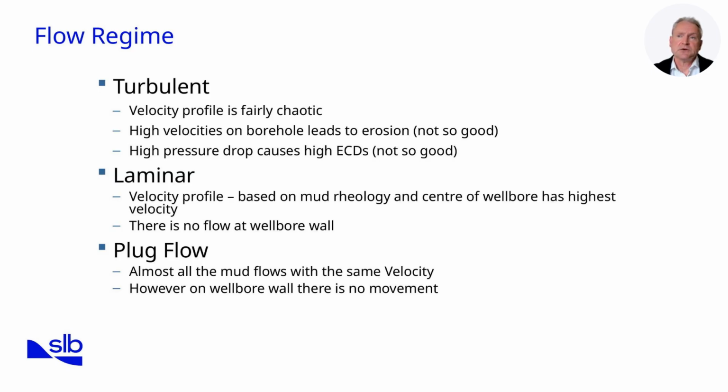Understanding these regimes is critical. In vertical wells, laminar flow may suffice, but in deviated or horizontal wells, turbulent flow is generally preferable to prevent cuttings accumulation. However, excessive turbulence may lead to erosion and higher operational costs. Hence, drilling engineers must balance rheology, pump rates, and annular geometry to achieve efficient cuttings transport while managing risks.